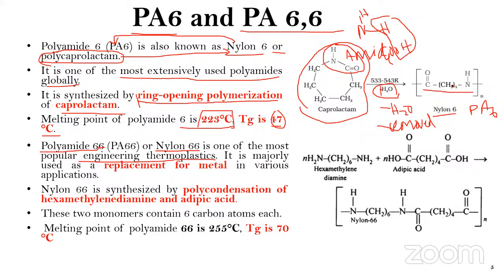See, the structure will not fail. First of all, due to the presence of water, you can get a lot of carbon dioxide which will be released during processing. It will not break your structure, but a lot of byproduct will evaporate. Can water sustain 200 degrees temperature? No. So that water will convert into vapor or gaseous form. Due to that, in your final product you can get some marks, or you can get some blister-like structure.